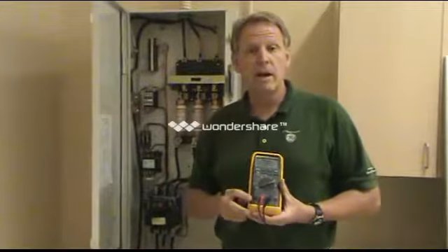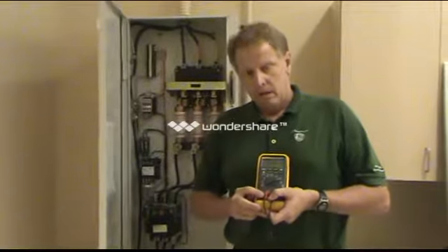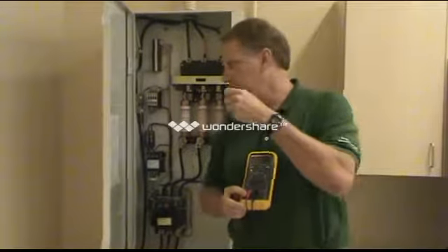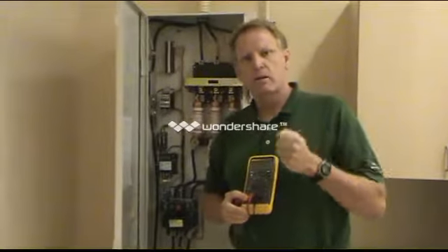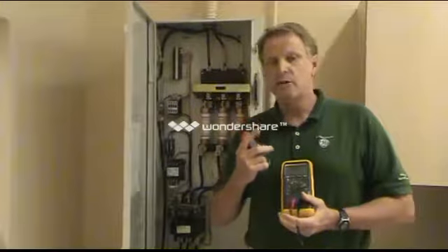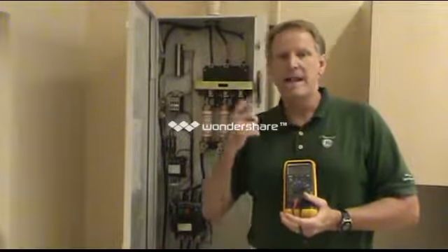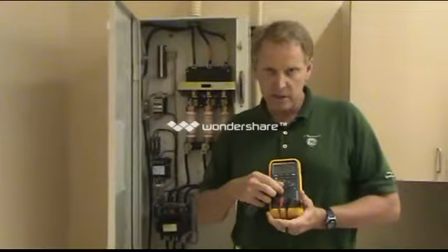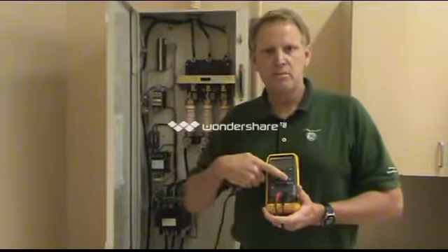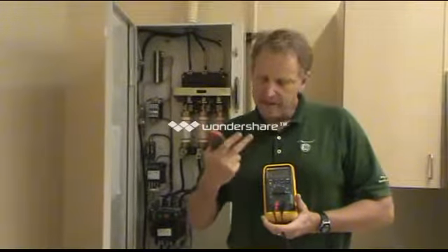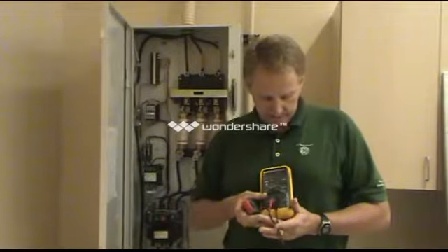All right, now ground currents is a little bit different. Ground currents we're going to measure on the facility side of the A1 panel, and we're also going to measure on the load side of the A1 panel. We're going to take 2 measurements on each, so with power on and power off. To do that, again, read the big red box on your sheets. You're going to change it to microamps. That gives us more sensitivity. If you leave it on milliamps, then the numbers are skewed a little bit.